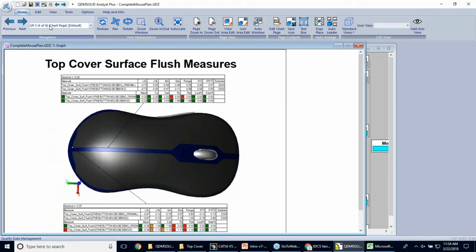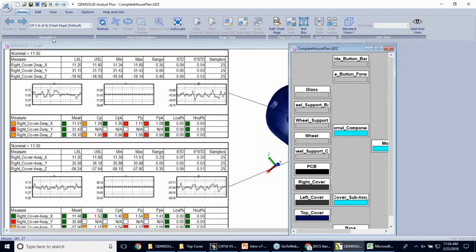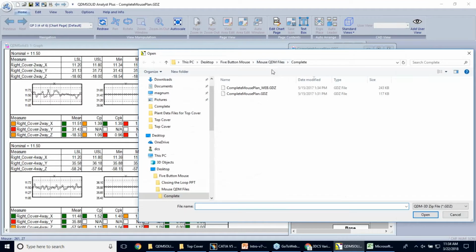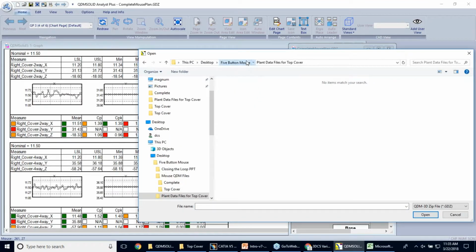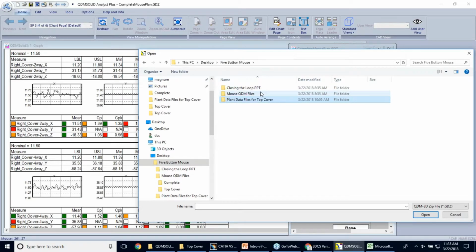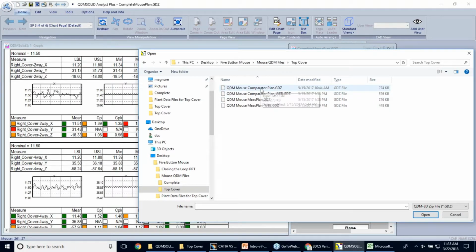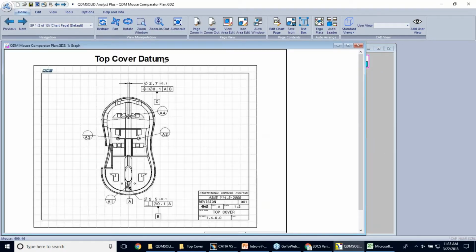You could have datum targets A1 through A4, and then different datum points F1 through F5. And then you have points that are measured relative to those datums. We would export the entire data set, all the points, and then the CMM operator would have to parse those out and write a separate program because he's got to set up to the other datum target points on the part.